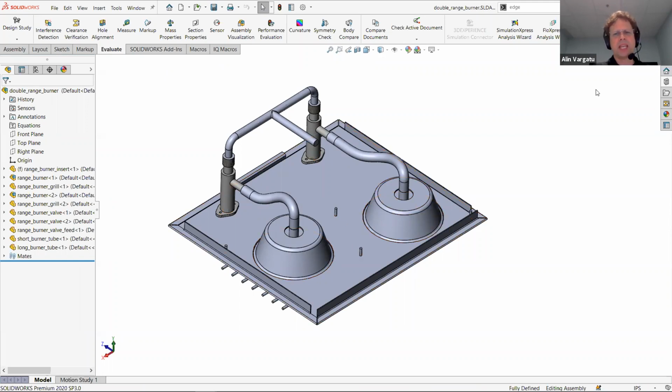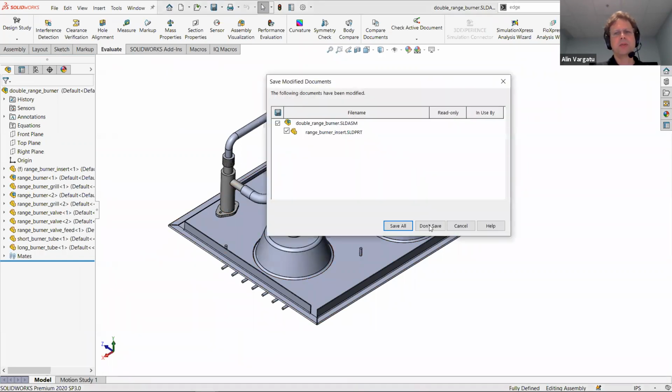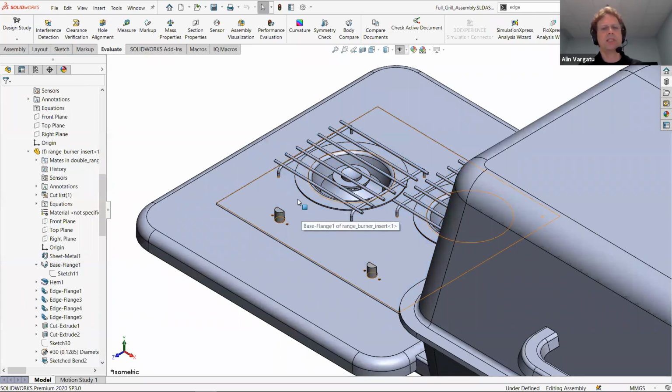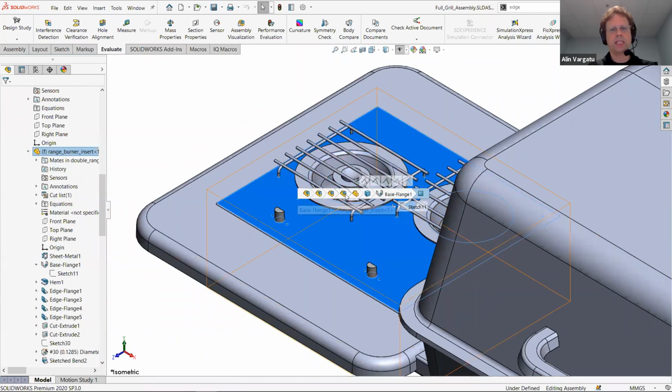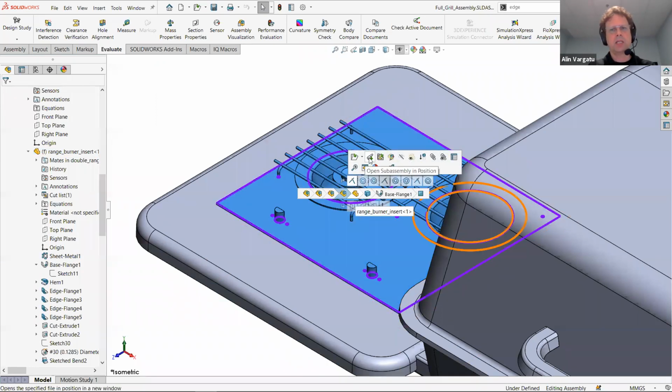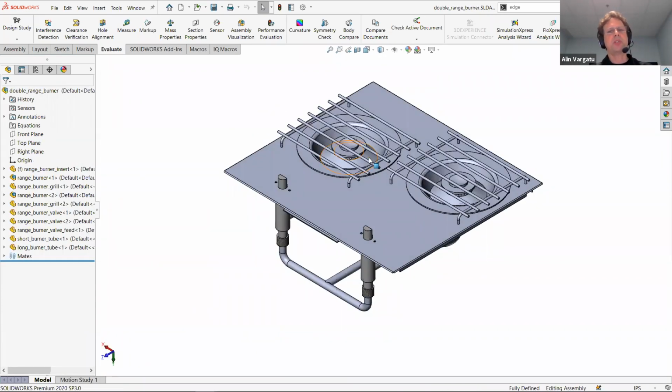Now, notice how it came kind of upside down. Doesn't look like the same assembly that I saw in my top level assembly. So let's try to use a different command. So this is the subassembly. And if you use this icon, it's going to open the subassembly in the same position that you have it in the top level, right? Pretty handy, especially when you deal with large assemblies and you're looking at this little part somewhere there. When you open it and it's in a different position, you kind of lose focus.